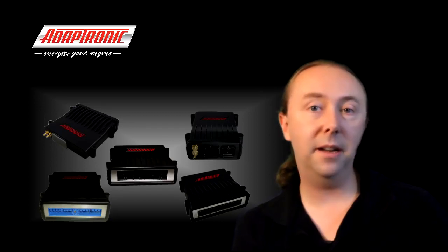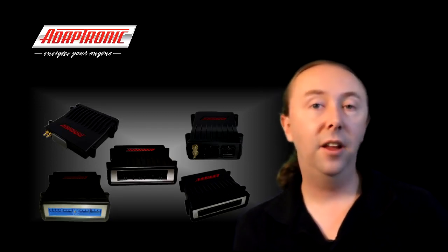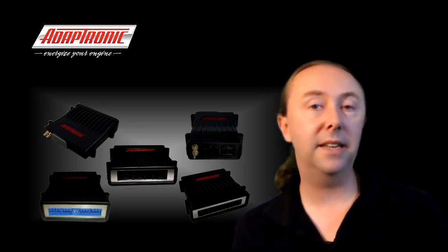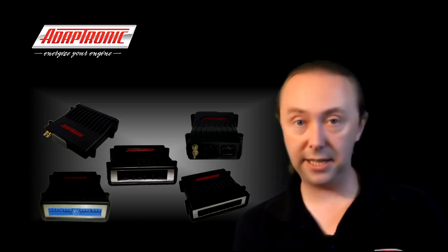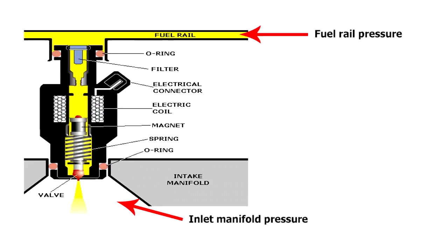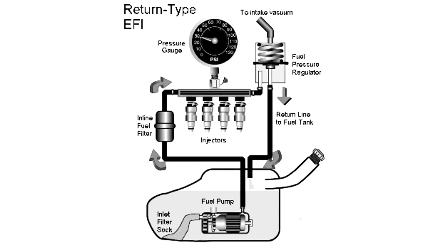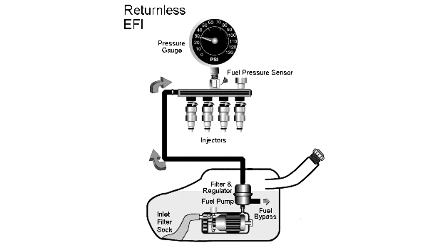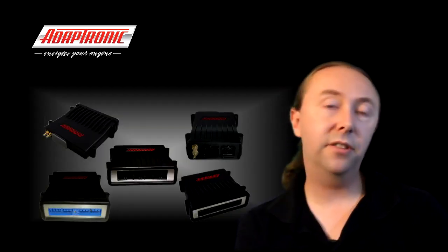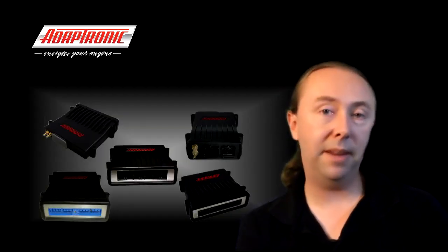Now in this description I'm going to be mentioning fuel pressure a lot, and when I talk about fuel pressure what I'm talking about is the differential fuel pressure across the injector. So the pressure in the fuel rail minus the pressure in the inlet manifold. If you have a manifold reference fuel pressure regulator, then this value should be pretty much constant. If you have a fixed pressure regulator, as in a lot of modern OEM systems, then the differential fuel pressure is going to change with manifold pressure.